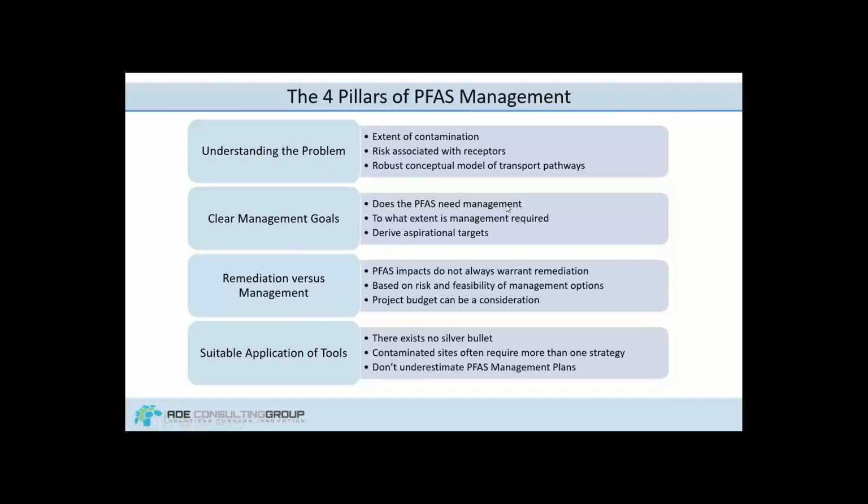If the answer is we do require some kind of management, right? Does the PFAS need to be managed? And to what extent is that management required? And then derive aspirational targets. The reason this is an important one is we need to make sure whatever we're putting in place is sufficient to arrive at those targets, whether it be mass flows off site that we're addressing, or concentration we want to have in the discharge water. Those will be the things that guide the decision, the technologies we employ, or the group of technologies we employ to address this.